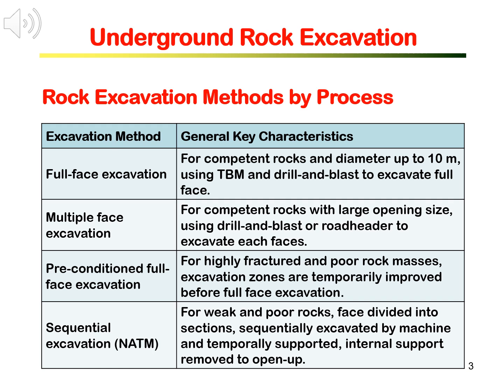But sequential excavation is done by installing support quickly after the excavation of each section to form a closed ring, followed by monitoring and eventually opening up the full face by removing the internal supports. We will have a session on sequential excavation, often referred to as the New Austrian Tunnelling Method, the NATM.